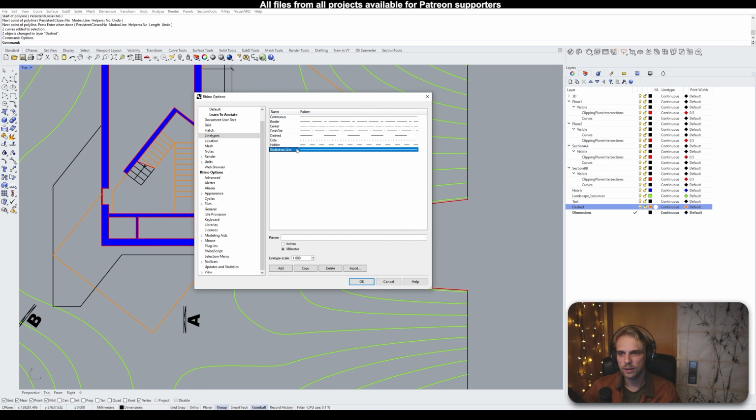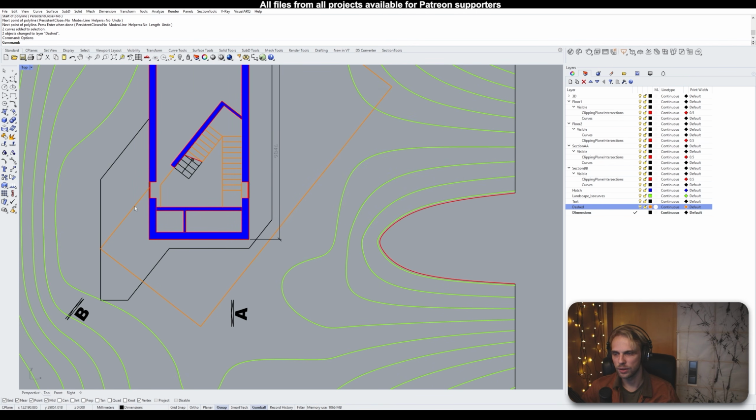In this case, we kind of want just a dashed line similar to this. So it's 5 by 5, and I will do exactly that. So let's do 5, comma, 5. Except that mine will have a line type scale set to 100, because I know that this is going to be my scale for plotting. So it's going to be like a 500 millimeter line and 500 millimeter gap in the drawing, right?